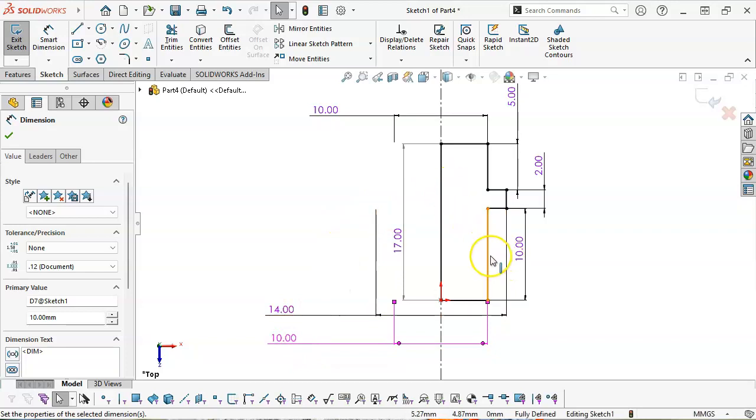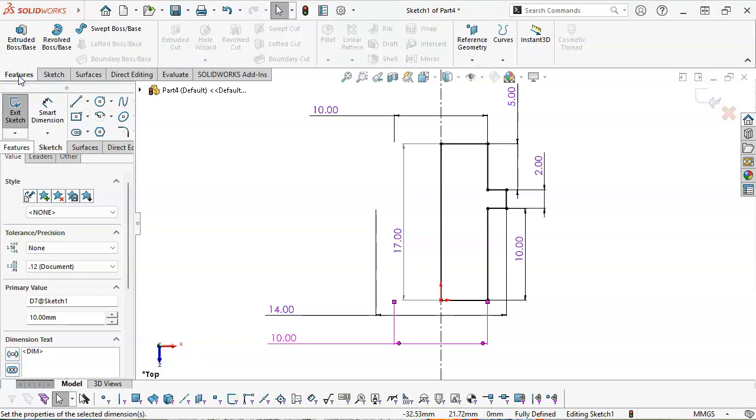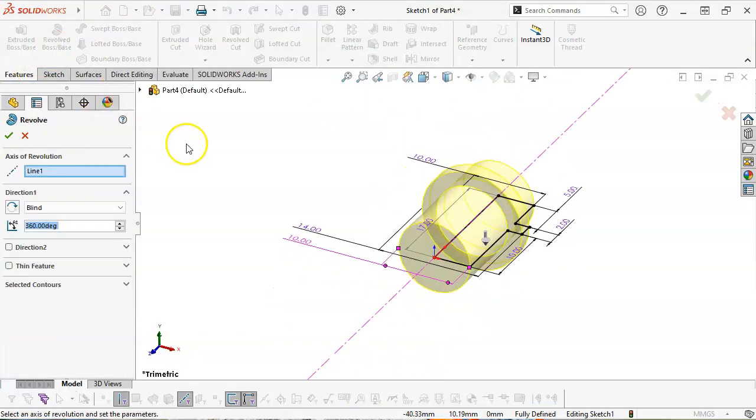All right, so this will be the press fit into the body, and then the crank or the follower will be rotating about this. And then when I press into the other side, one of the 5 millimeters, and because if they both rotate and it's not really a bearing surface, yeah, there's going to be some scoring, galling, heat. You know, the functionality is going to be, life expectancy is going to go down quite a bit.